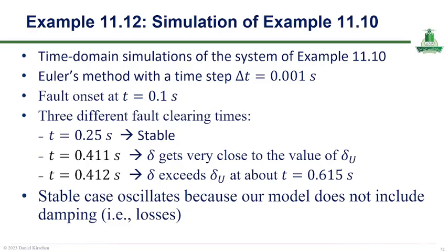This slide presents the time domain simulation result for the system studied in example 11.10 using the Euler numerical integration method with a small time step of 0.001 second.